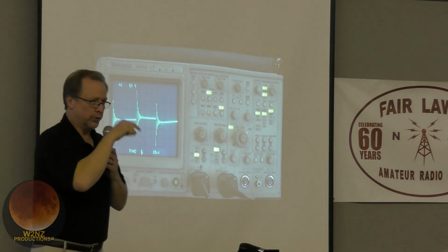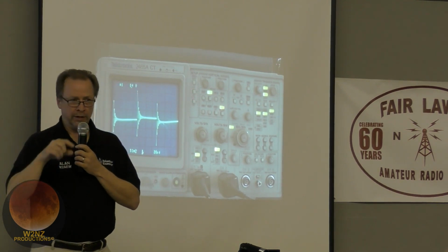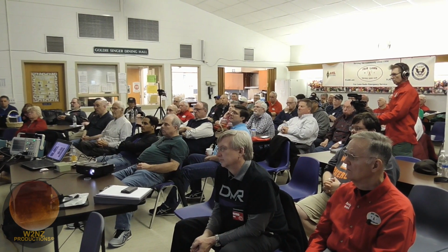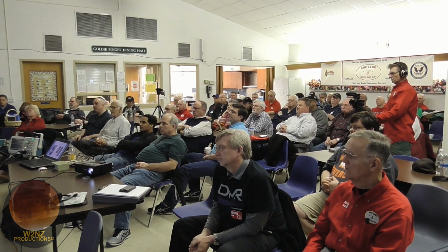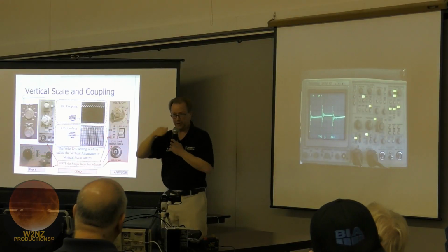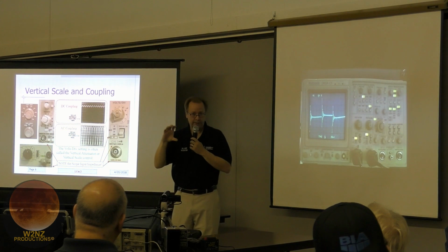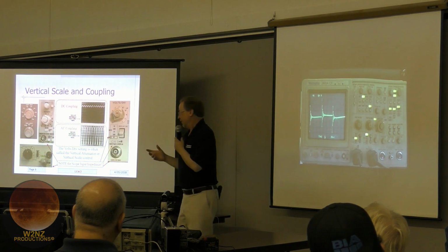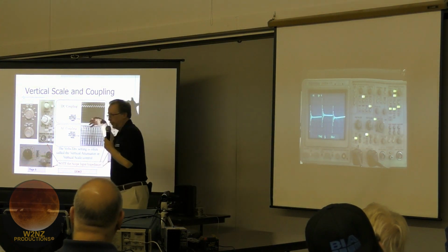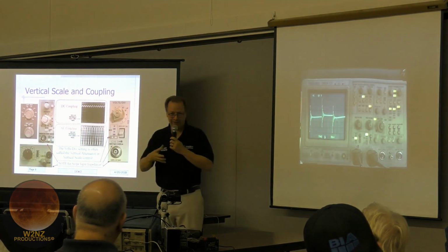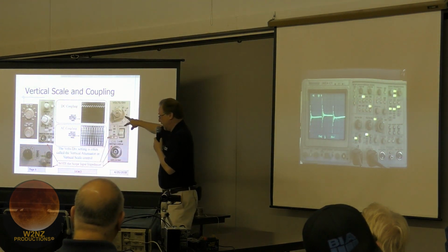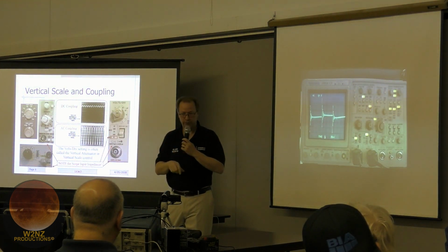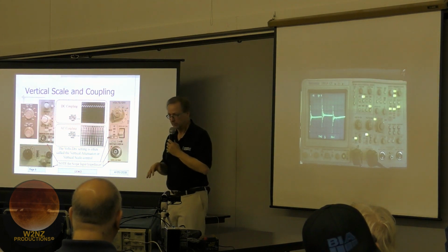If you're probing through, say, an audio chain in an amplifier, and your audio is getting clipped, if you're AC coupled, you really can't tell why. But if you DC couple through that amplifier, you can see that I'm clipping at the top here because my audio is hitting the supply rail, or it's saturating a transistor. If you're AC coupled, you really can't tell what's going on, but if you're DC coupled, you can see the bias on the transistor as well as the signal. So, like I said, sometimes we use DC coupling on AC signals and AC coupling on DC signals. So don't think of those as the type of signal you're looking at, but think about what it's doing and how it's coupling the signal into the scope to actually go take a look at. Everybody good on that? Okay.